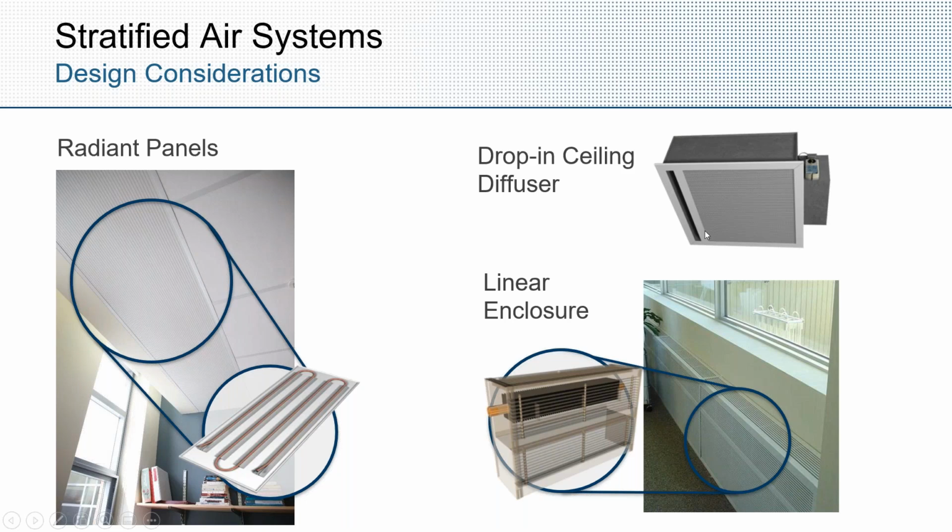The caveat to this is that if you're designing a DOAS, dedicated outside air system, or you're looking at downsizing your outside air through that ventilation effectiveness credit, if you're heating using a mixed turbulent type of approach in heating mode and not one of these radiant natural convective heating approaches, you have to consider that when looking at your overall mechanical footprint, because now you have to consider the air distribution effectiveness in the heating mode as well.